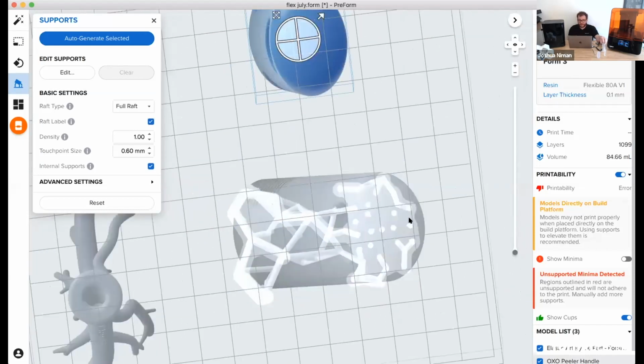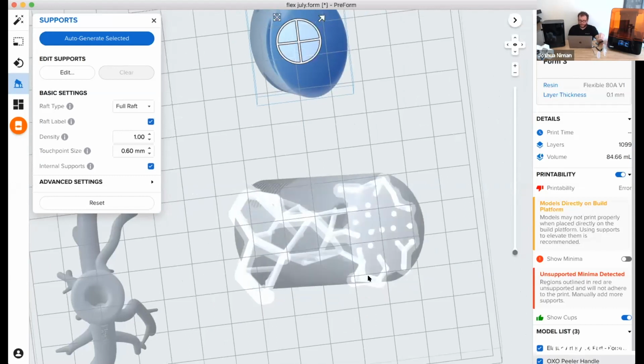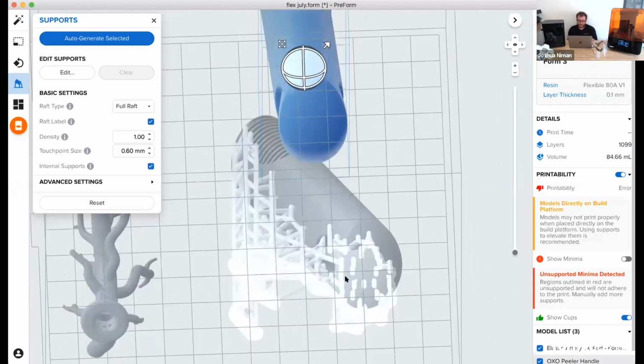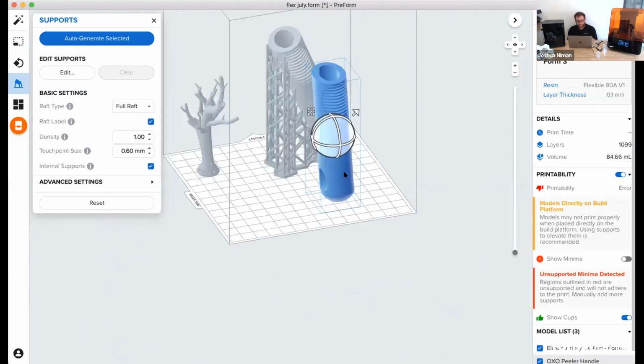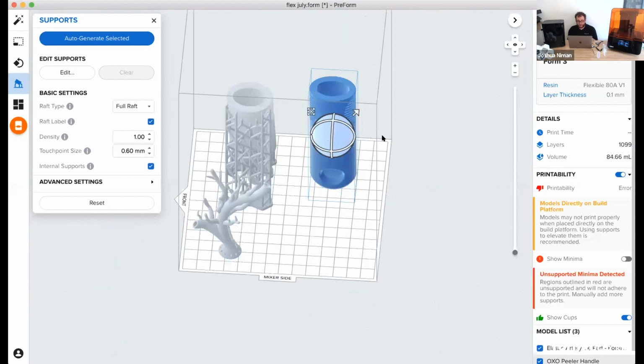And you can see I've sort of done this here. This is the lowest point on this orientation I've chosen, and then I have sort of a raft which comes and forms two legs at either end up here. And I have good support throughout the entire length of the part. This is a pretty vertical orientation I chose over here for a soft material.